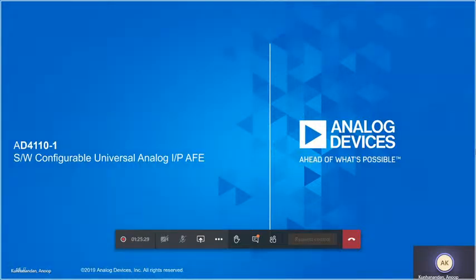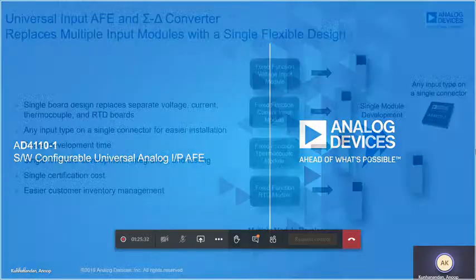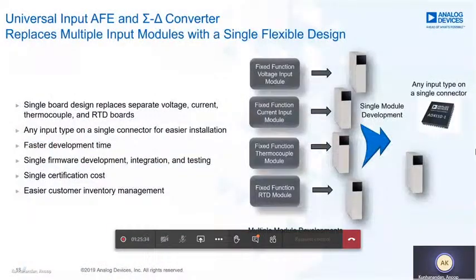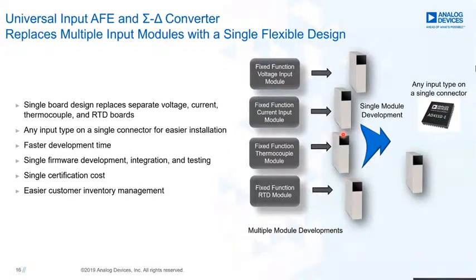There could be applications wherein you may need an input module in the PLC which needs to measure a voltage input, or a current input, or a temperature input like thermocouple or RTD. Traditionally, when you look at the design, you have to have different hardware, as I mentioned earlier, and different software.